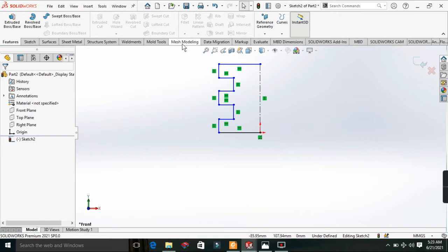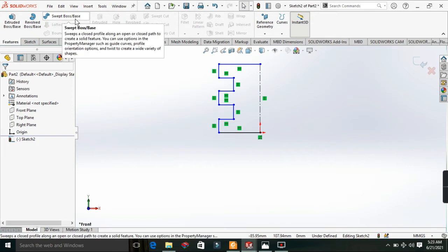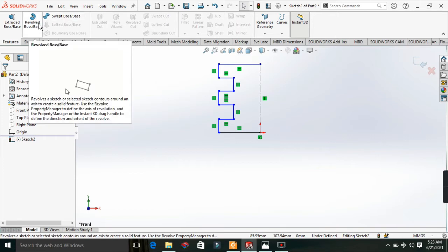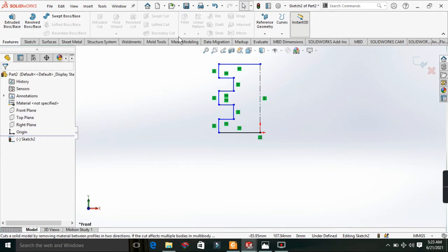It will show in English the names of the icons, what you want to perform. So it will make it easier for you. The word revolve means revolving round. It has clarified that it's different from extrude boss. Do you understand? So the next thing we do is you go back to the diagram and you dimension your work.